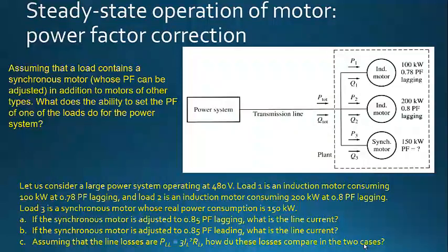We made mention that synchronous motors have the ability to operate at both lagging and leading power factor, and thereby can be used to improve the power factor of a power system. Now we are going to solve one example and see how synchronous machines or motors are used to improve power factor in a power system or in an industry.